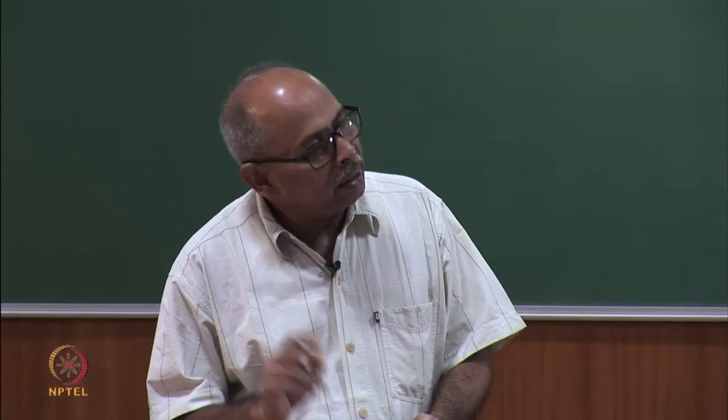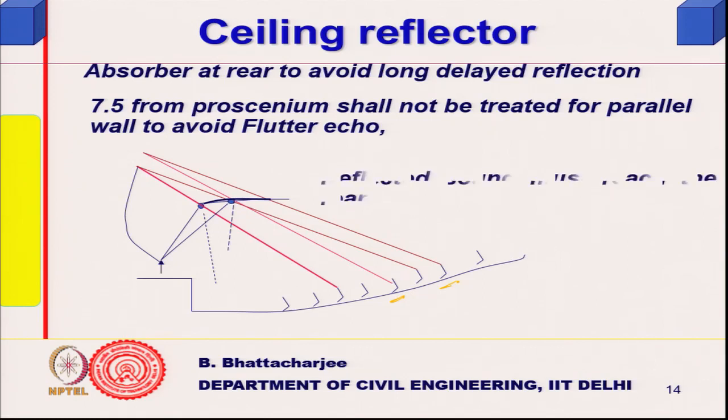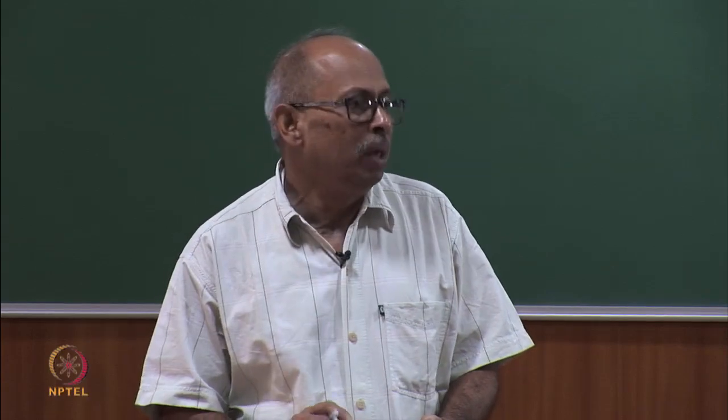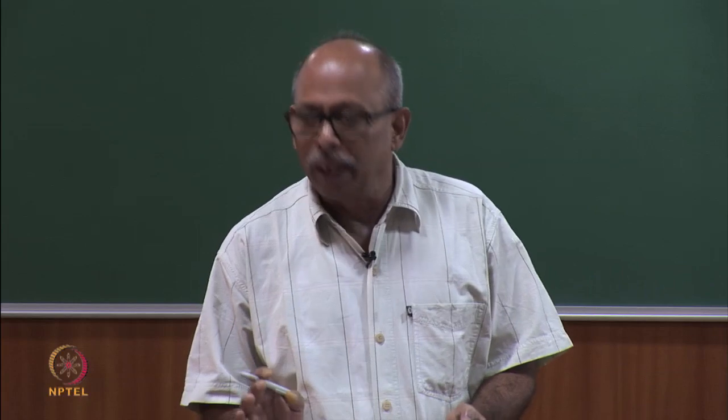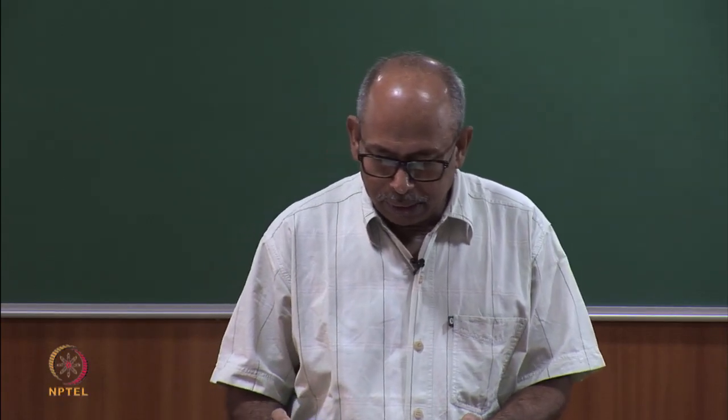So, that is how the ceiling reflectors work. Reflected sound must reach the rear from the ceiling, or even from near the proscenium wall, it should reach the rear, and should not come back. Therefore, no parallel wall, right. So, that is what it is.